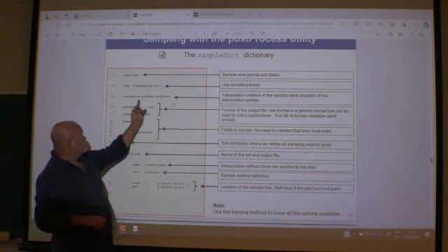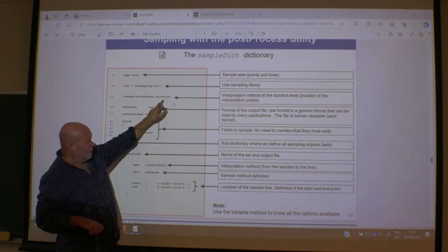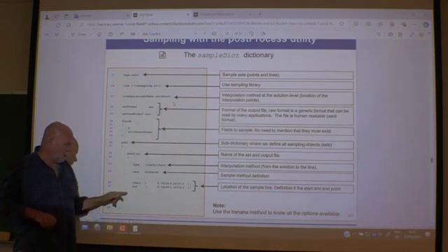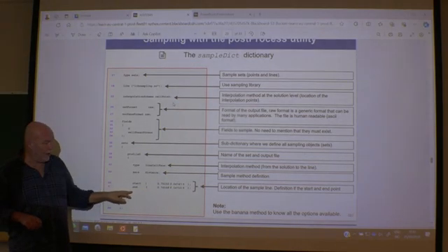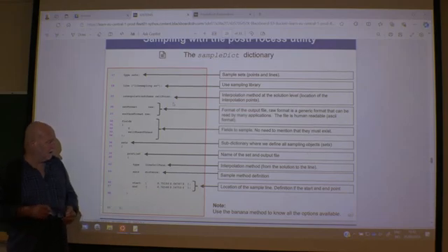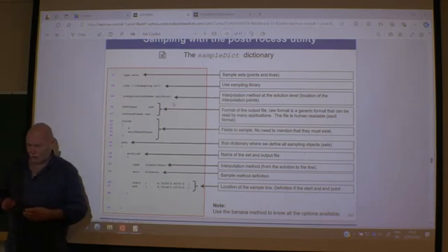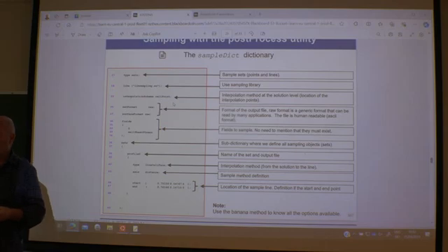So interpolation scheme, cell point. So instead of specifying I want 100 points or 1,000 points along this line uniformly distributed, it will only take your cells. So this is also a good idea for how you can extract data from, say, the original location, from the cell centers only, for instance. That's actually possible here.